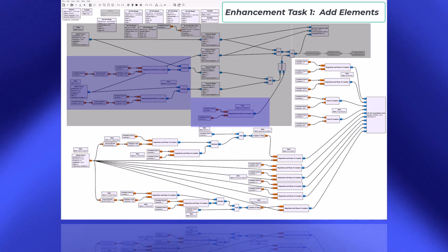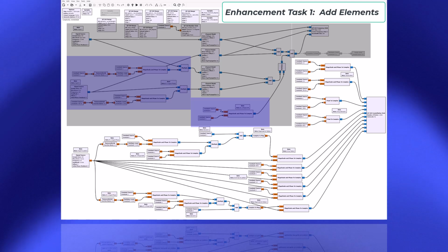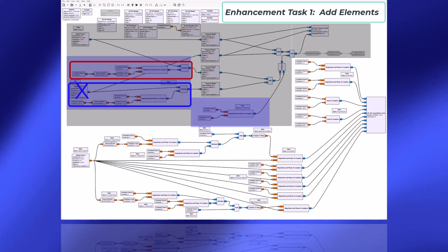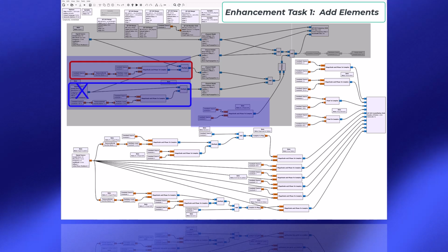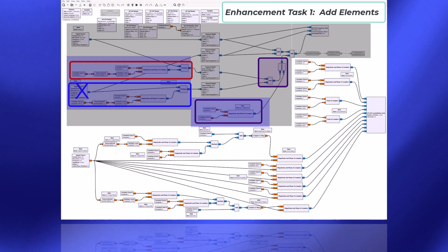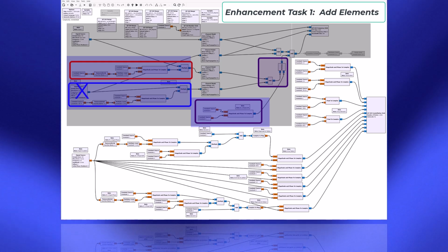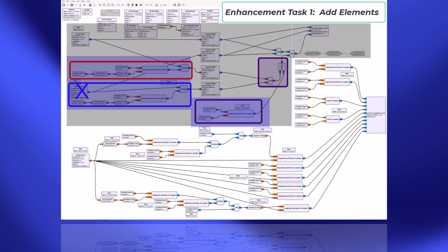That is, you will need to apply a phase shift at each new element that represents the effects of the geometry. So that would be this series of blocks here and this series of blocks here above and below the second signal source. Additionally, you'll have to apply a phase shift to the combined signal at the new element, and at each new element you'll have to do this. That phase shift will be related to the selectable phase shift in the current simulation. However, it will also depend on the spacing between the elements.